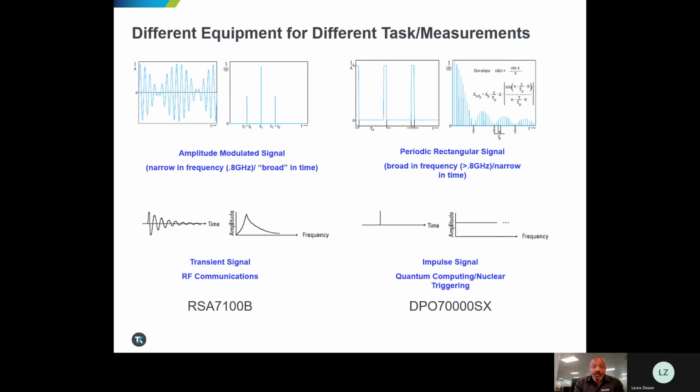These are critical in order to describe the rise and fall time and overall shape, the squaring of this signal, which needs to be analyzed in the case, say, of a clock, to make sure that you can trigger the event in the amount of time that's needed in order to ensure that precision and timing is kept within the instrument under test.